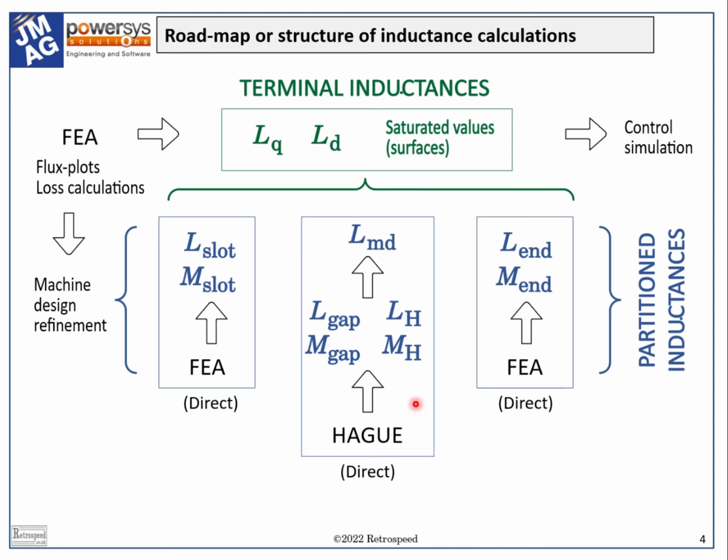And the inductance associated with that fundamental space harmonic of the armature ampere conductors is the so-called magnetizing inductance, LMD. Other space harmonics of the armature ampere conductor distribution produce flux linkages at the fundamental time harmonic frequency, but contribute nothing to the mean torque.